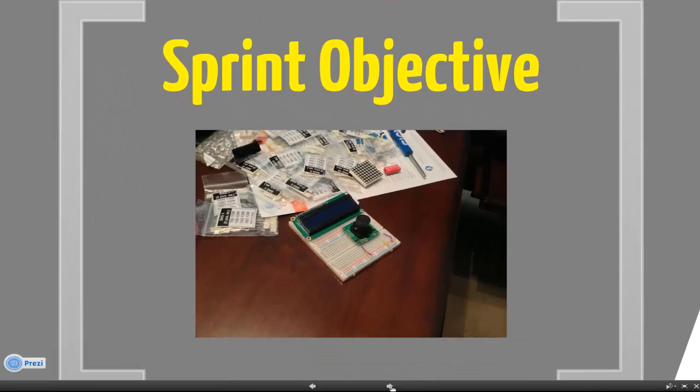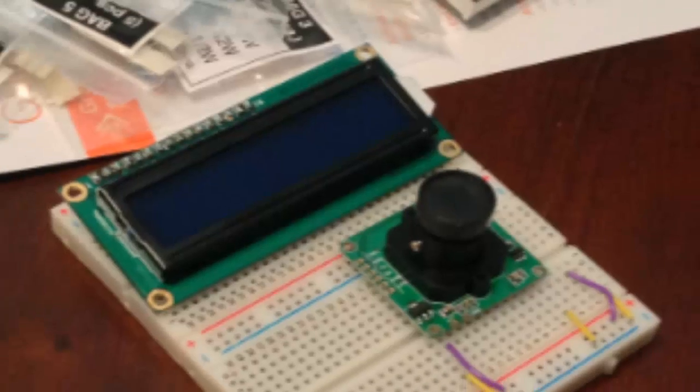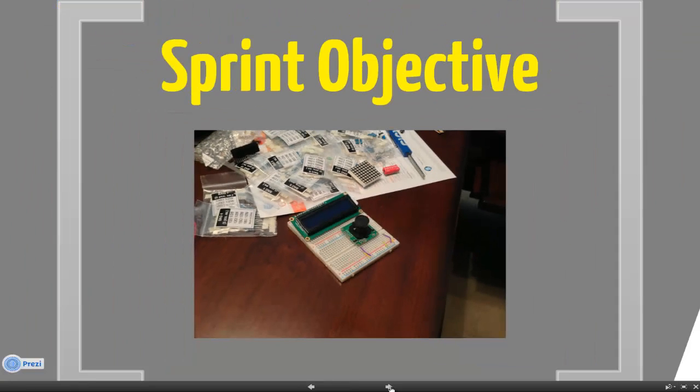For this sprint, our objective was to produce a prototype capable of capturing a non-static biometric identification image. To create the prototype, we are using an Arduino microprocessor controller, high-intensity LED light matrix, a TTL JPEG camera board, IR proximity sensor, various IC drivers and registers, a small project box, and a PC to receive and process image data. We are still missing some components this week, but the majority of them have arrived. We have provided some images of the early breadboard work and screenshots of the code.